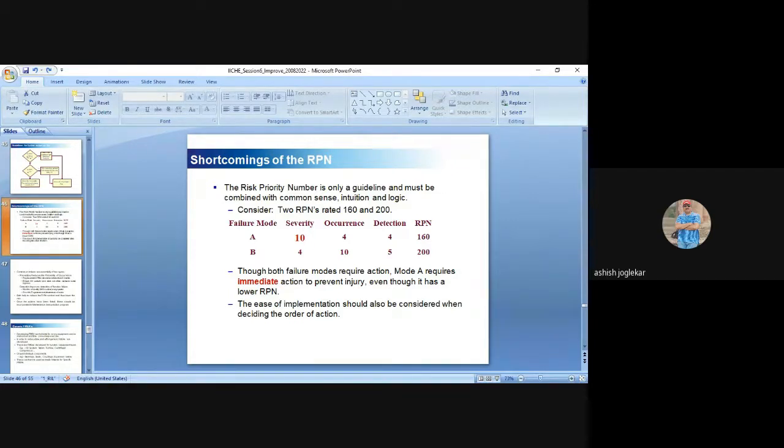And the top 4 or 5 causes are taken for taking actions or improving those causes. When you sort in descending order and take the top 80%, say you have 30 causes, 30% is around 3 or 4 causes. Not more than 5 generally we take. So let us take the top 4 causes.